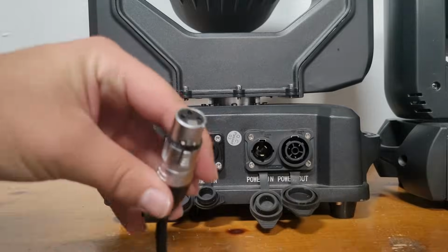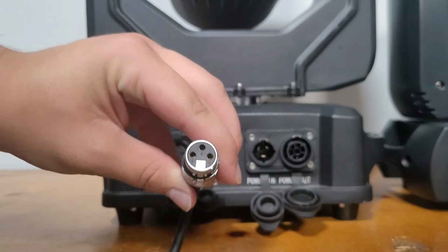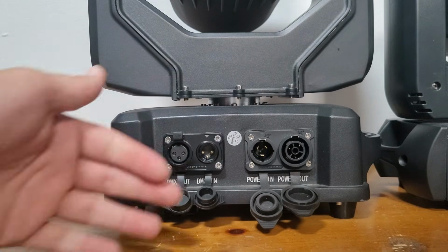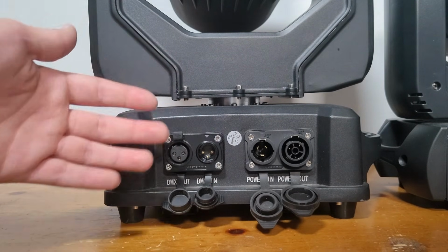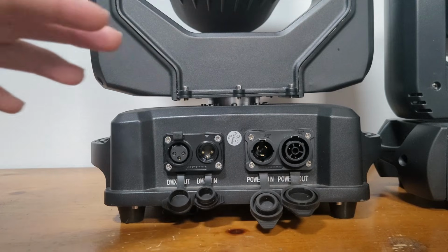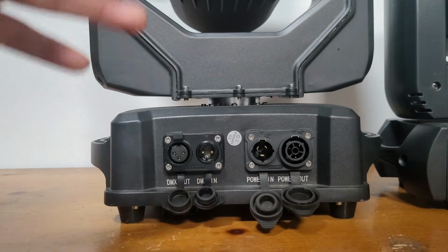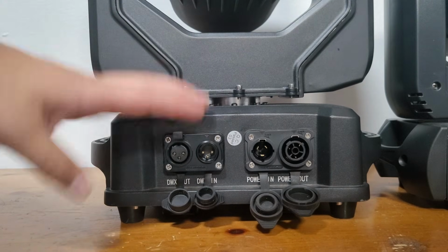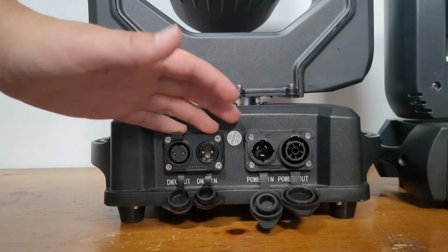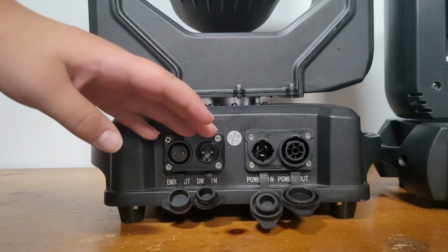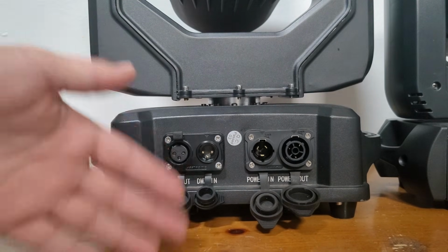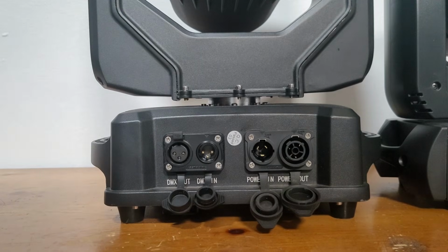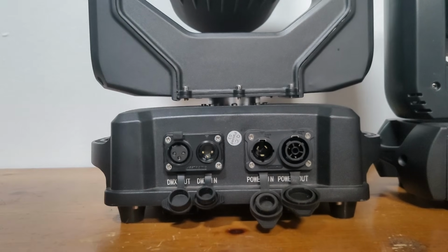Now a big mess up you might make is that these connectors are the exact same used for microphone cables. And you might think you could just get microphone cables to connect DMX products together. But that is a big no-no because the impedance rating on them is a lot different. Microphone cables are for sending analog signals, whereas DMX cables are for digital signals. So you want to make sure that you are specifically buying DMX cables, because if you plug in microphone cables, you'll have a lot of problems. The signal won't work half the time, and I just don't recommend it. So make sure you get DMX connectors.